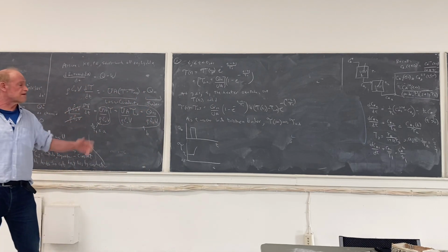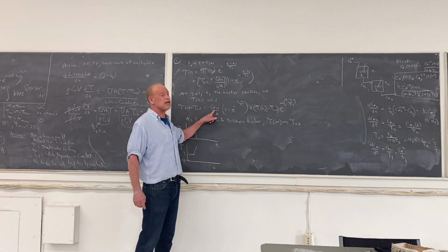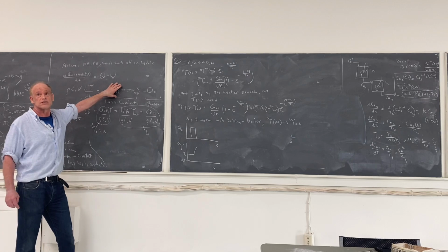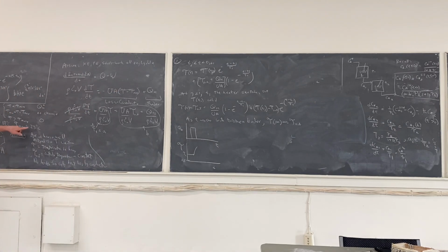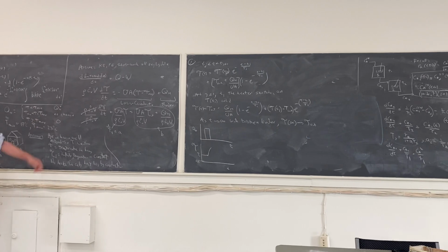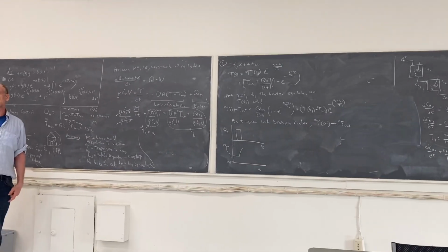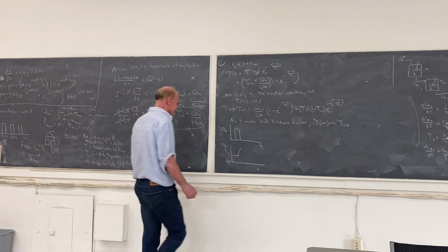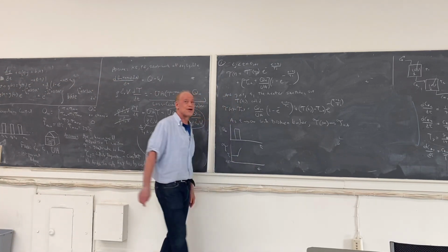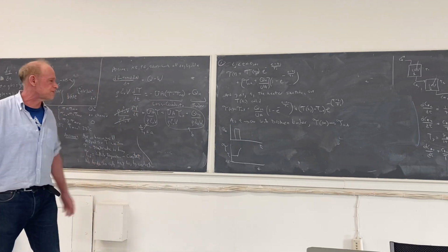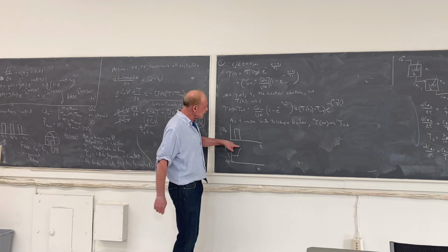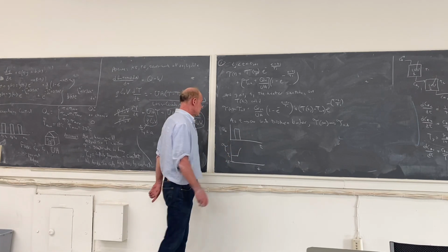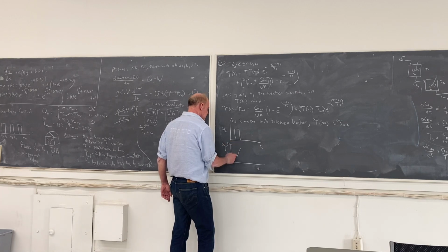It will eventually level off because eventually the heat from the heater will balance the heat loss. But that could be way above 23 degrees. That could be at 40 degrees centigrade. And you don't want to sit at 40 degrees centigrade. I've been in 50 degrees. You don't want to be in 50 degrees centigrade. 50 degrees centigrade is about 120, 121 degrees Fahrenheit. Okay, so now I get here, and what happens? The heater goes off because I've hit 23 degrees. So this is say 23, and this is 17.